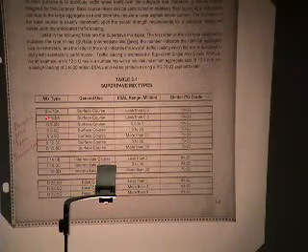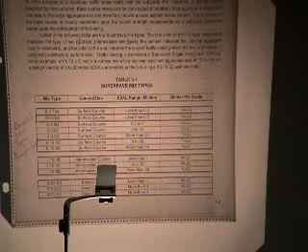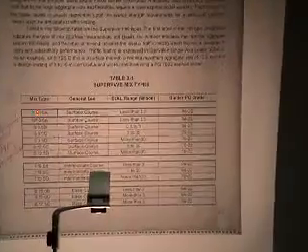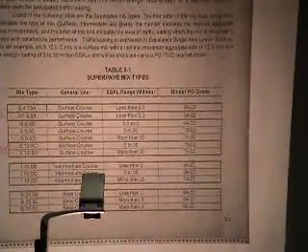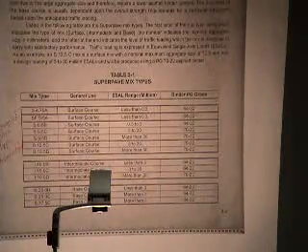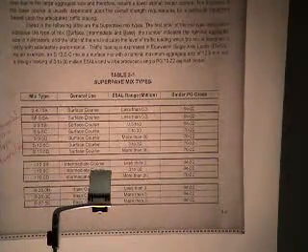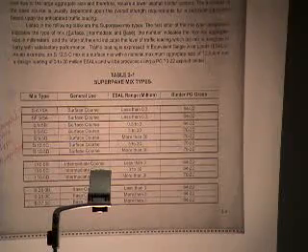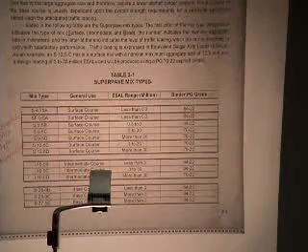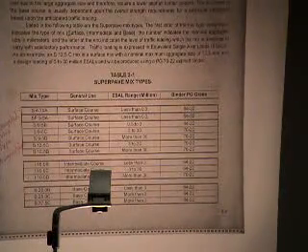There is one exception here, and I'll talk about that in just a minute. But in every case, the letter is followed by a number. That number is related to what is called the nominal maximum aggregate size in that mix, not the maximum, technically, what's called the nominal maximum.